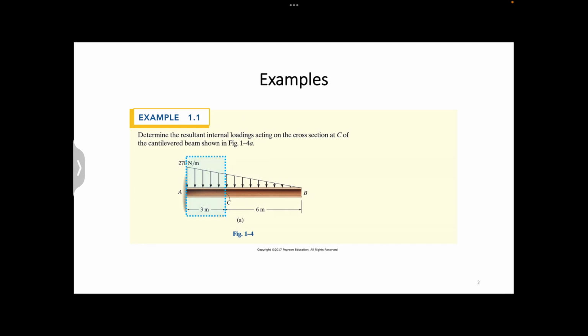As such a process is quite time consuming, now we will see whether we can save some times and efforts by considering the right segment. Because there are no supports on the right segment, it is true that we can plot the free body diagram for the right segment without the need of finding support reactions. Because of that, we will now decide to proceed with the right segment.